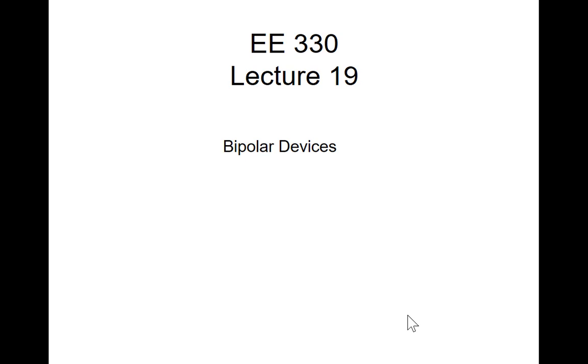Last time we talked about a process flow, a CMOS process flow. Any semiconductor process has a flow that can be described somewhat like we did last time. And what's the reason for knowing the basics about a process flow for a given design? What's the reason you need to know what that process flow is? Yes? It changes your calculation. It changes your calculations? Yeah, and it also affects what you can connect and what you can't connect. Yeah, that's the most important thing. It shows what you can do and what you can't do.